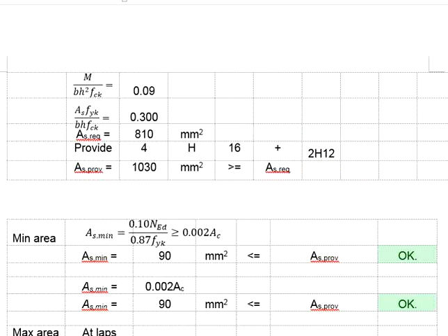This brings us to an important understanding. The arrangement of the reinforcement, you must always cross-check with the directions of the moment. Make sure those reinforcements are actually contributing in resisting the moment. You can't simply put them there.